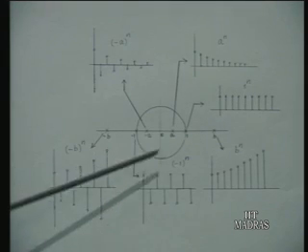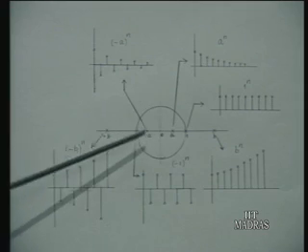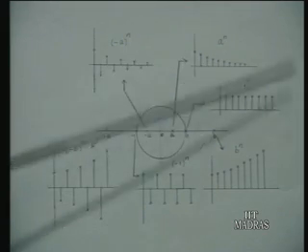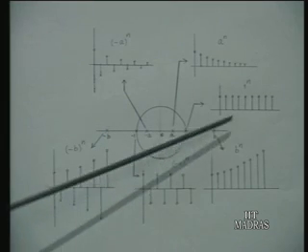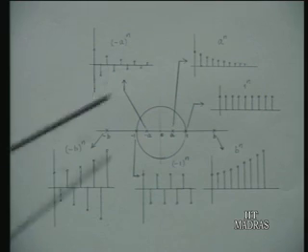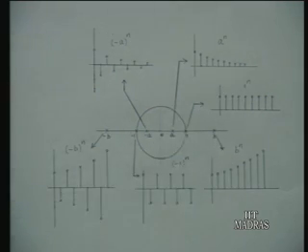On the other hand, suppose there is a pole at z equals a, where a is less than 1, then it will be a to the power of n, a decaying type of response. If there is a pole on the real axis at a distance greater than 1 from the origin, this is a rising response, so it goes up like this.